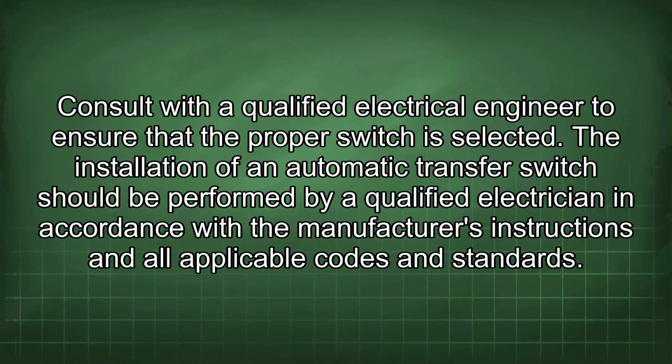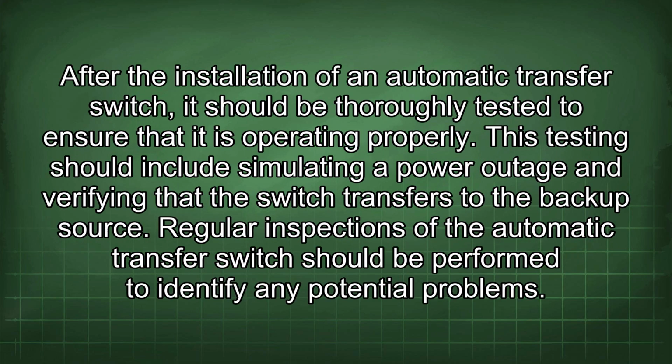The installation of an automatic transfer switch should be performed by a qualified electrician in accordance with the manufacturer's instructions and all applicable codes and standards. After the installation of an automatic transfer switch, it should be thoroughly tested to ensure that it is operating properly. This testing should include simulating a power outage and verifying that the switch transfers to the backup source.